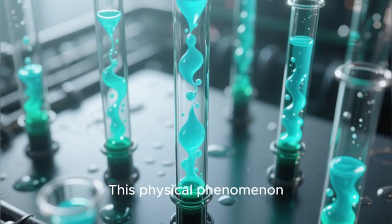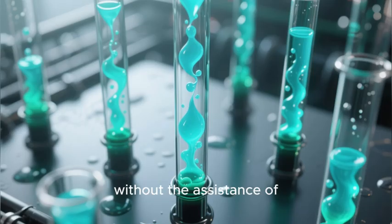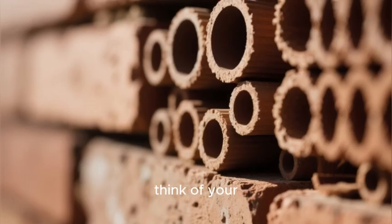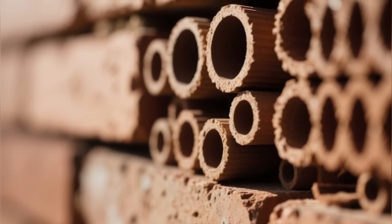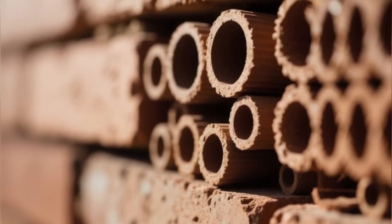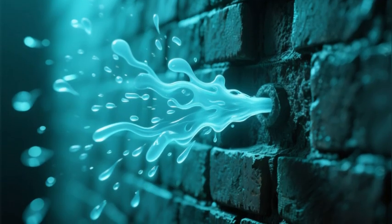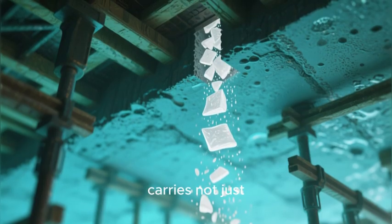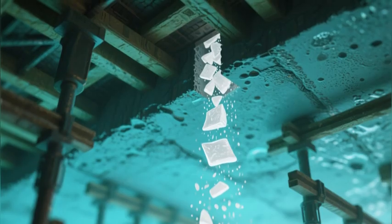This physical phenomenon occurs when liquids spontaneously rise in narrow spaces without the assistance of, or even in opposition to, gravity. In building terms, think of your masonry materials: bricks, concrete blocks, mortar as containing millions of microscopic tubes. When these materials contact moist soil, they naturally wick moisture upward through these capillary channels. This rising damp carries not just water but also soluble salts from both the ground and the construction materials themselves.